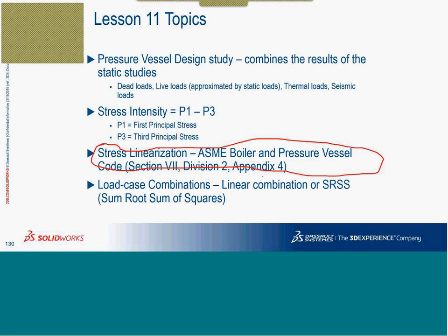But those codes are not using FEA to solve the details. They concentrate only on one thing, stress linearization, with their own ways of calculating linearized stresses, and they directly jump onto that particular localized thing.